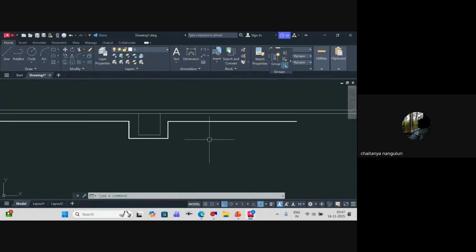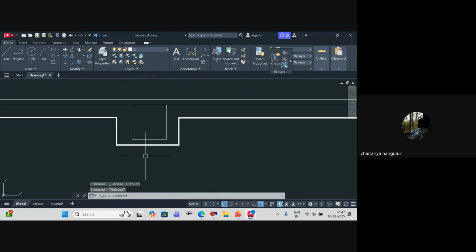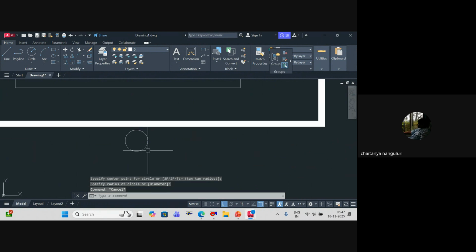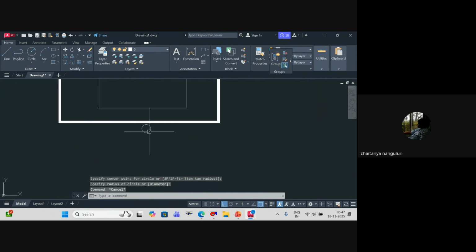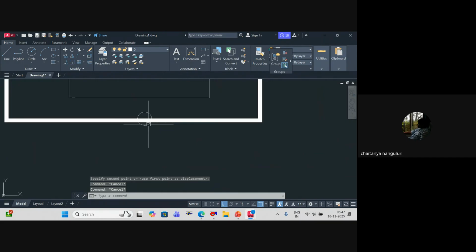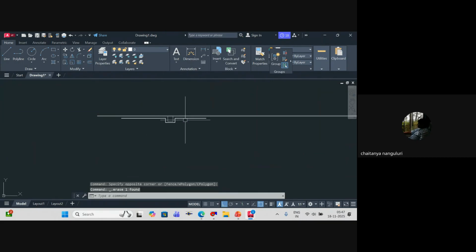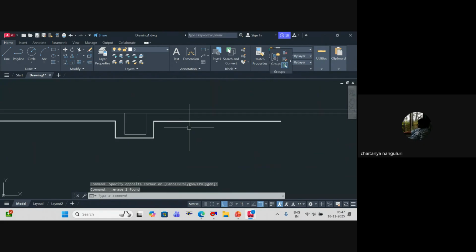Understood or not? If you have a beam exactly underneath without any column parallel, take it exactly near the beam, because the beam itself will act like a fire barrier, right? Generally you have columns exactly at the intersection of the beam. That's the reason we don't do it. Or else you can take your pipe something like this. Understood? So 150 like that, you can have a gap, but not like 2 feet. It's not allowed. Understood?